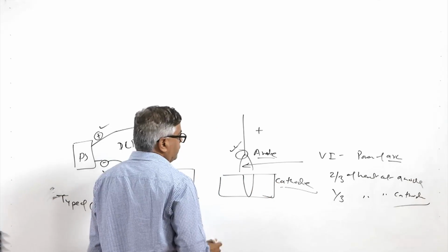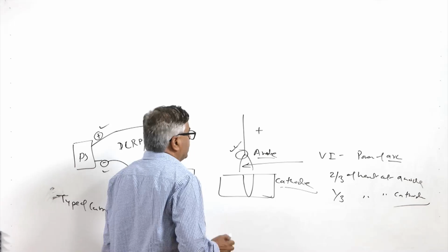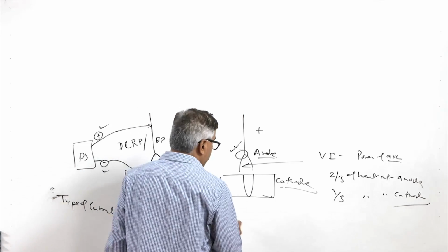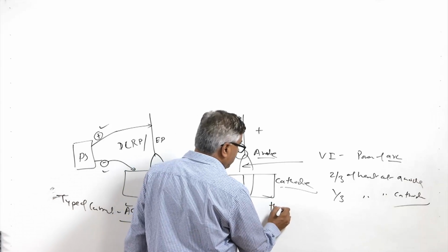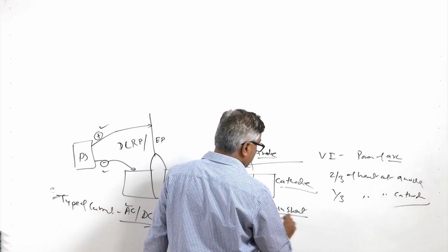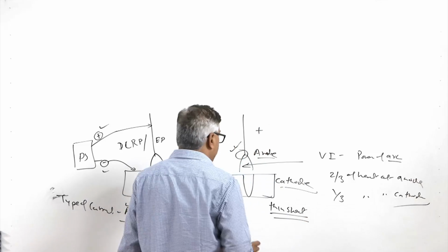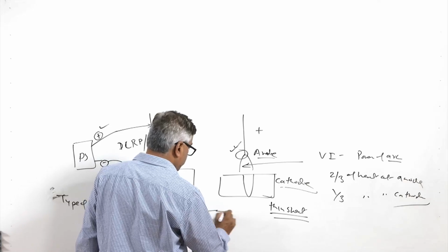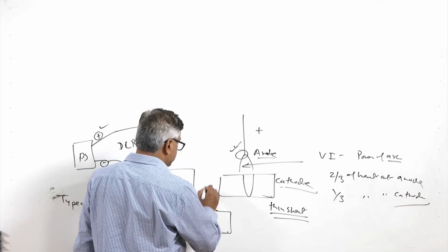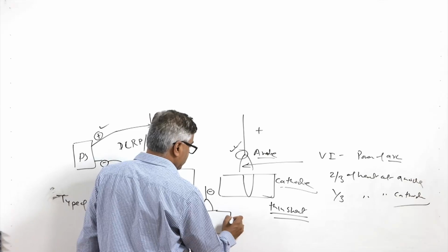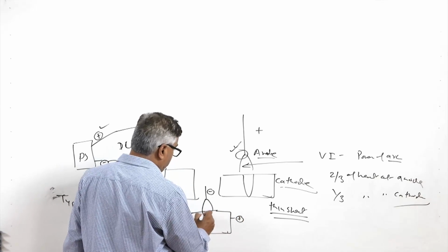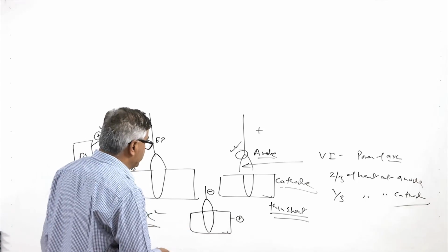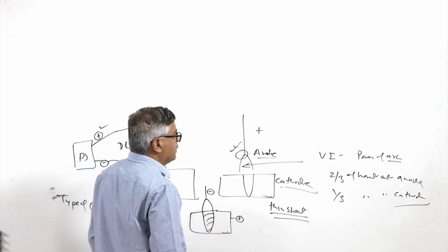So, in this scenario, more melting of the electrode will occur as compared to the base metal. This leads to melting of the electrode at a much faster rate than the base metal. This may be good when thin sheets or plates are being welded, but when we are working with thicker plates, we normally prefer electrode negative and workpiece positive, so that more heat is generated on the workpiece side to ensure penetration through the thickness of the plates, so that the required weld can be obtained.